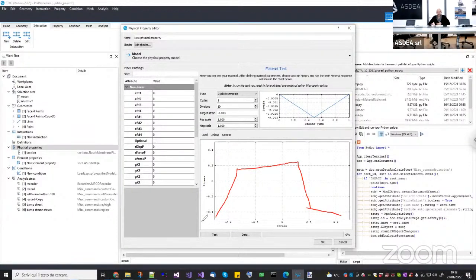Once you have this one, this also defines the bending stiffness at the base, which can be different from the elastic bending stiffness of the pile, and the yield moment. Eventually you can have a little bit of hardening and a drop in the moment rotation graph, and then a residual plateau. We gave some examples on this one.